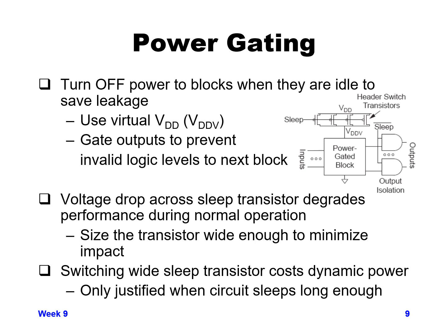Now, when you know that that logic isn't being used, you can have sleep go to a value of 1. It turns off the current through all of those transistors, and that entire block will now act like it's got a stack of PMOS that's turned off in series with it, and so its overall leakage will go down by a factor of 10 or potentially more, depending on what the internal logic is.